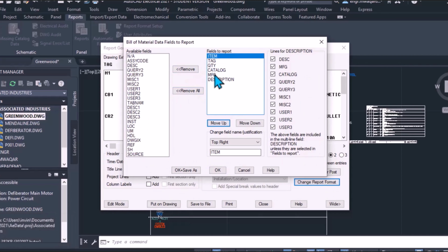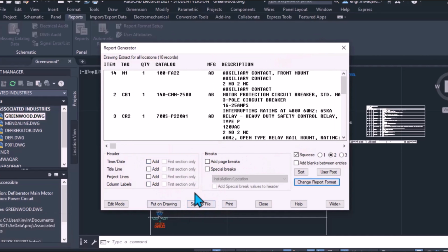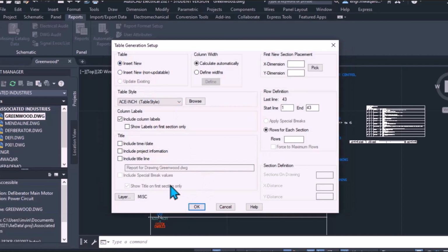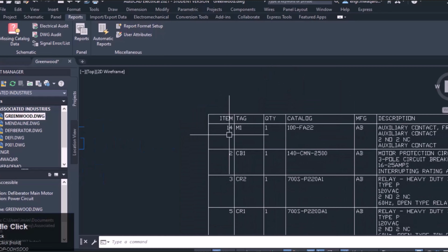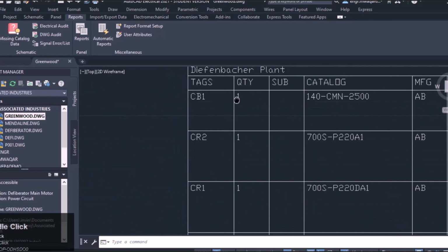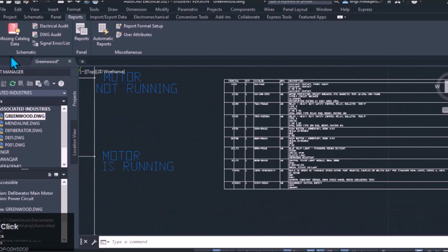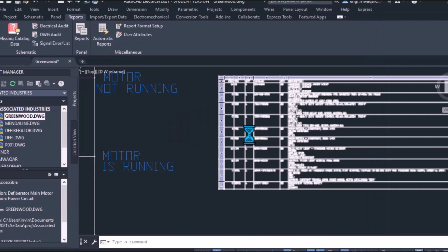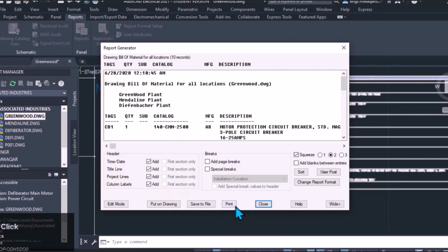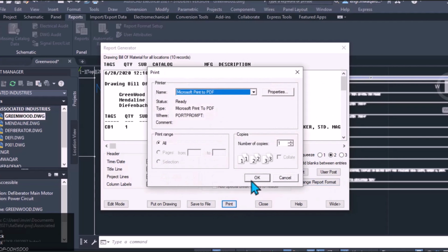Okay. Let's look at a real-world scenario from the tutorial. You're reviewing your generated table, and you suddenly realize that certain components, say a push button labeled PB6 and an overload safety component, are completely missing from the report. They just aren't there. Hold on, that doesn't make sense to me. If I'm the engineer and I physically select a push button from the menu and draw the circle for it right there on the screen, the software sees the button.